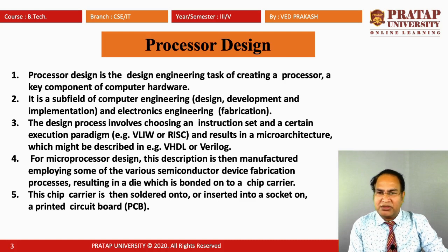The design process involves choosing an instruction set and certain execution paradigms such as VLIW or RISC, and results in microarchitectures which might be described in VHDL and Verilog. For microprocessor design, this description is sent to manufacturers, implying various semiconductor device fabrication processes and resulting in the die, which is wound onto a chip carrier. The chip carrier is soldered onto or inserted into a socket on a printed circuit board, that is known as a PCB.